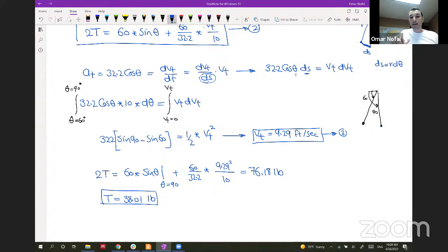And actually this is interesting. If you are solving this swing as a static problem and you have a weight here that is equal to 60 pounds, then the tension here will be 30 and the tension here will be 30. But solving it as a dynamic problem and including the dynamic component will increase the tension in each cable by 8 pounds. And this is because of the normal acceleration generated by your movement on this curve.